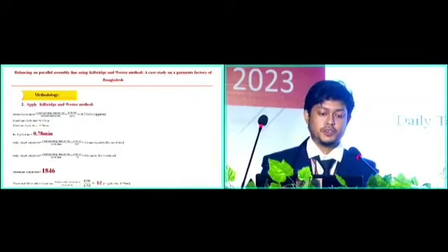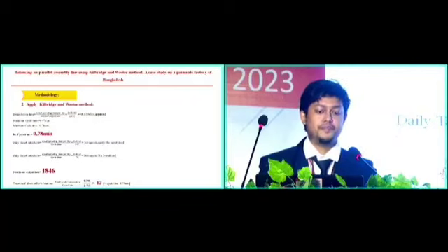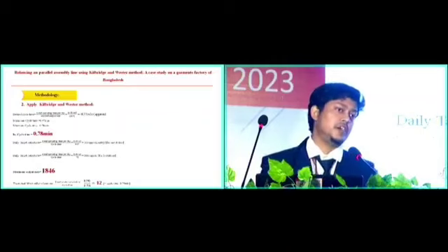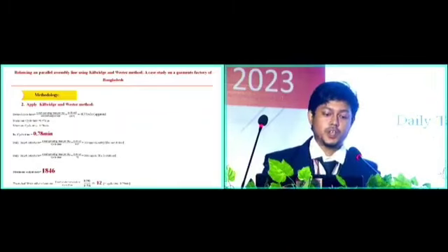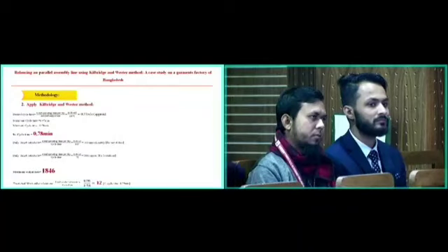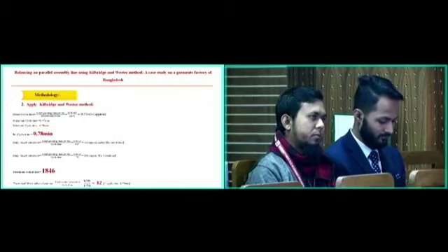Daily target output rate equal to total operating time per day divided by cycle time, equal to 160 approximately for one station. If we calculate 24 stations, we have found 1,846 approximately. So maximum output rate will be 1,846.